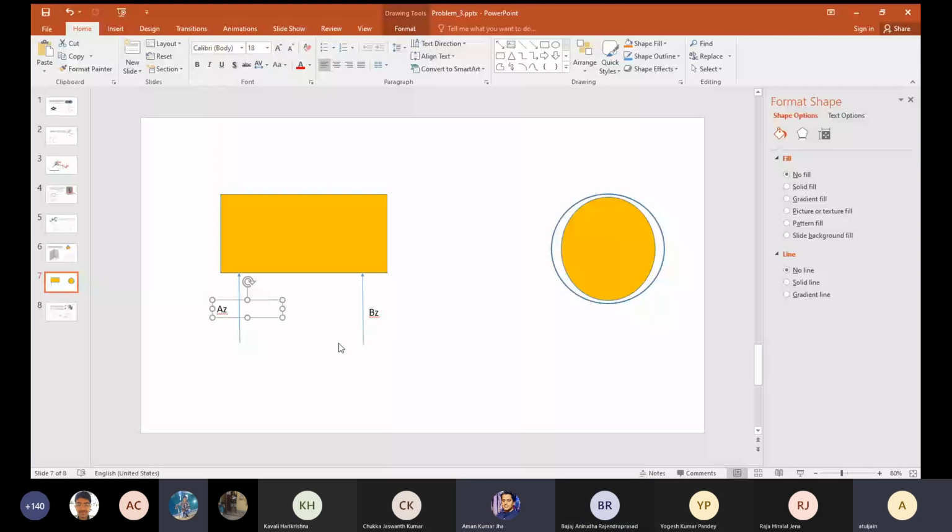Sir, while drawing the free body diagram, only these two forces will come? No, we have to consider only one ring at a time. Whenever you are drawing a free body diagram, irrespective of whatever constraint you have, only look at the constraint, understand what translations and what rotations are allowed and what are not allowed, draw the reactions for that constraint, and individually go one constraint at a time. There are only very rare cases where you will look at both the constraints together.